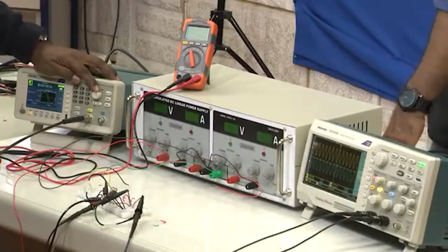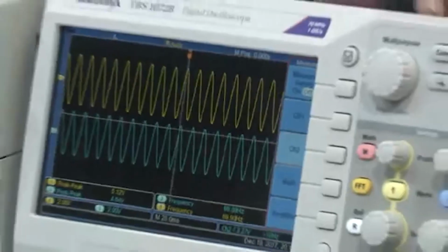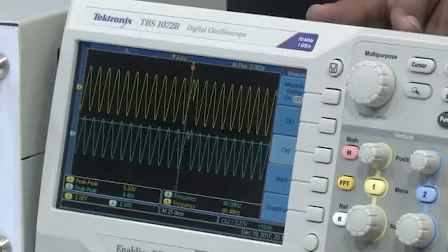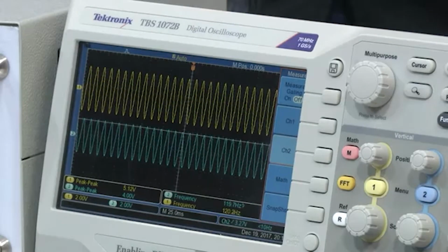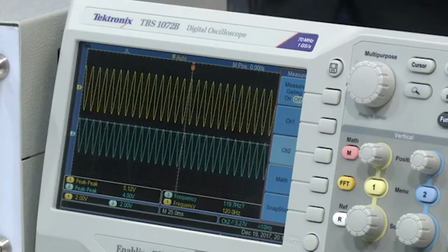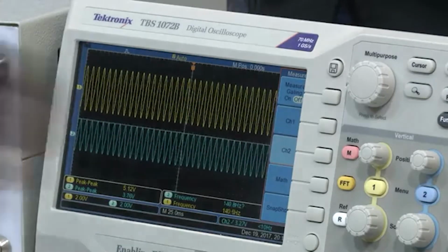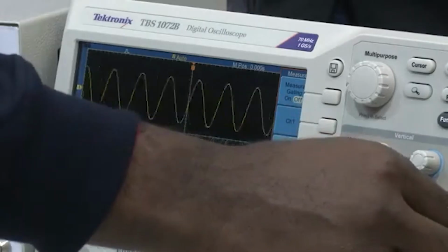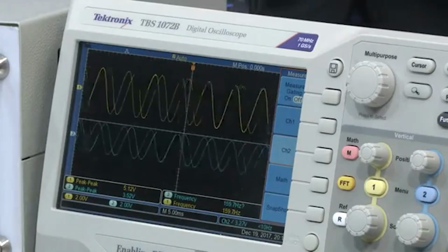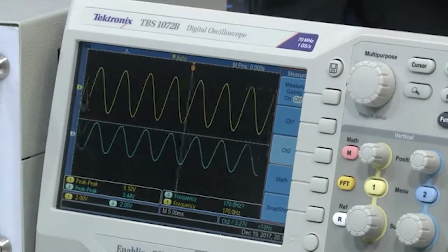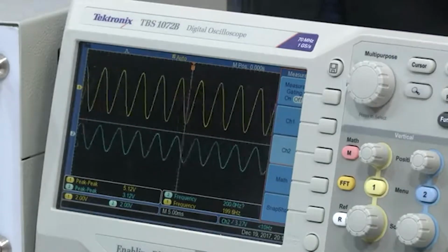Okay. So we are increasing the frequency to 60 hertz. You can just look at the oscilloscope, he is increasing to 60 hertz, 90 hertz. So slowly, 100 hertz, still you can see it is following, 119, 120, still following 120, and now 150, and suddenly you see that the amplitude is getting clipped, or the amplitude is decreasing, right.